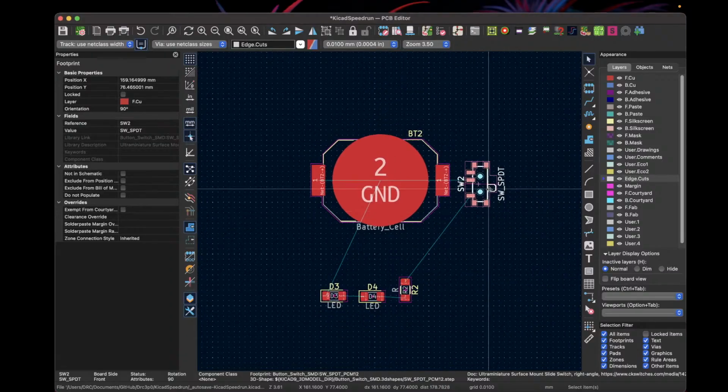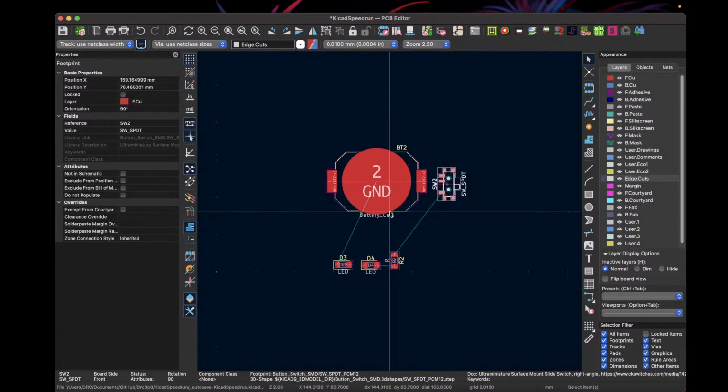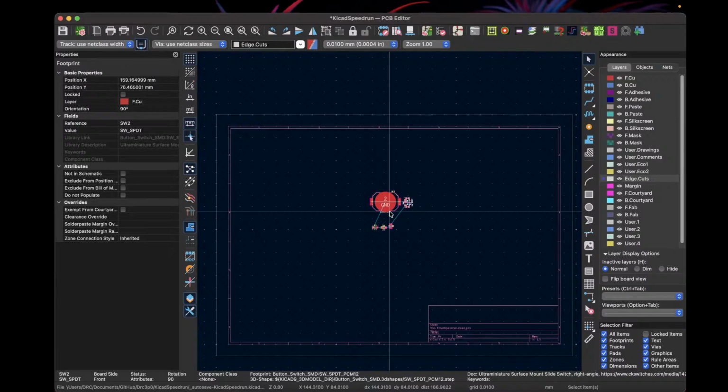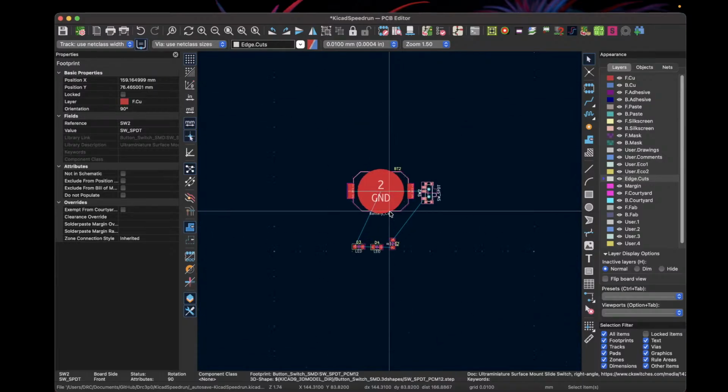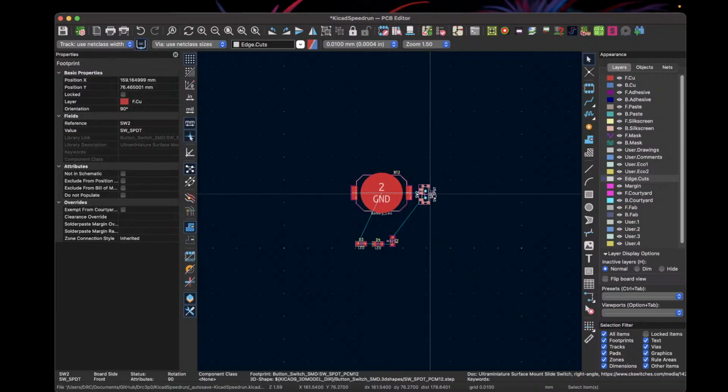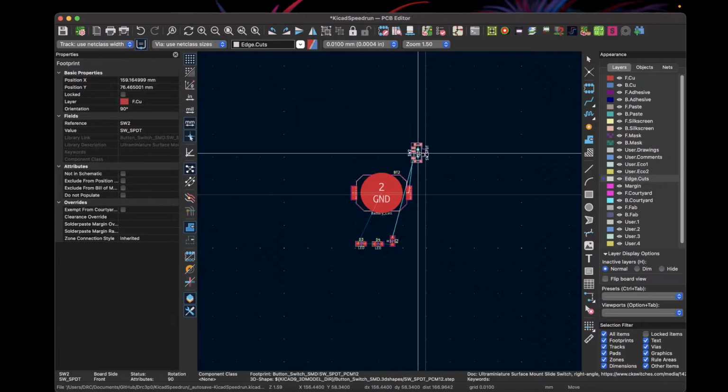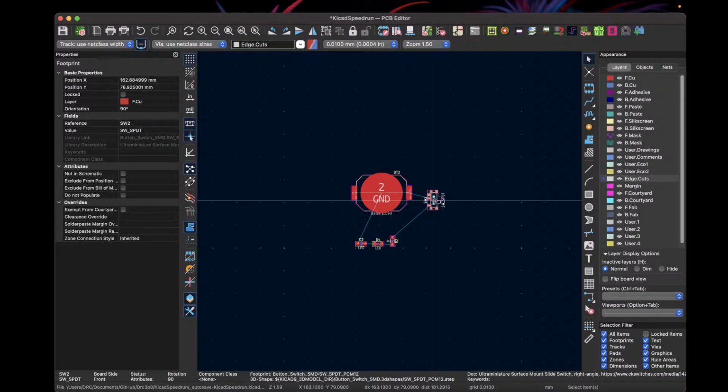Yeah, there is also an auto routing feature in KiCad, and it's funny that in 2026 it's still not very good. So even today, even in this modern age, most people working with circuit boards will insist on doing it by hand still. But there are some shortcuts for this that I can show you. So the layout is the main consideration, just like how messy you can get. Yeah, and especially if you're working with like a microcontroller or high-speed data lines, some of those, it's very important for it to be really short.